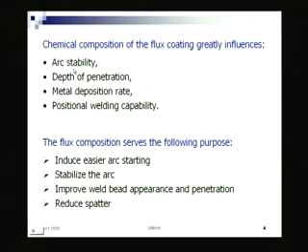Arc stability means what? That means the arc is nothing but a plasma column. The gas in that gap between the metal plate or the job plate which is being welded and the electrode tip, whatever gas is there, to start with it's only atmospheric air, right. Now, unless you have the circuit closed, current will not flow. So, if I just hold the electrode like this, nothing will happen, isn't it? You may have observed, you just touch it and then lift it up.